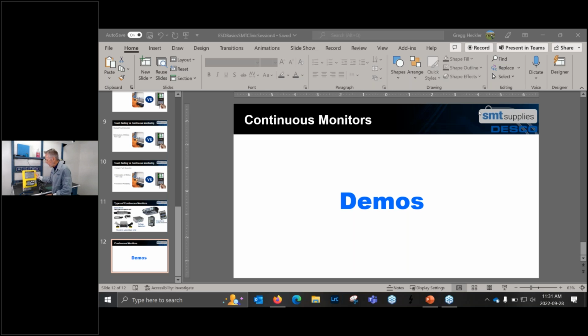So this is your basic. This one we call a combo tester X3. This one we can test the wrist strap, and I don't have the plate connected because I'm not talking about foot grounders, but this device actually tests all three devices with a single press of the button. So I'm gonna just, oh no, I can put it on my band, I'm sorry.